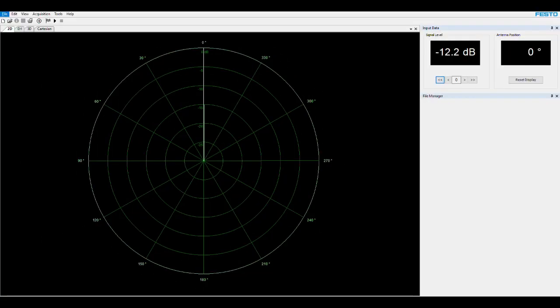In this lab, we're going to take a look at what's going to happen if we increase the distance between transmit and receive antenna. To do that, let's start acquisition of an E-plane pattern of a half wavelength dipole antenna. And then we're going to do the same thing, but this time we're going to increase the distance between transmit and receive antenna. This beep that we have in the background shows that the transmitter is on and the system is ready to record the pattern.